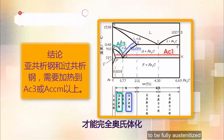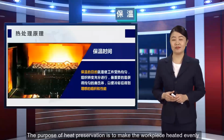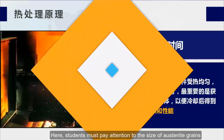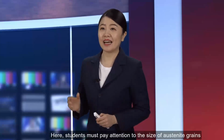To be fully austenitized. When the heating is over, keep warm. The purpose of heat preservation is to make the workpiece heated evenly, the structure transformation is fully carried out, and the most important thing is to obtain uniform austenite, so that the ideal structure and properties can be obtained after cooling. Here, students must pay attention to the size of austenite grains.